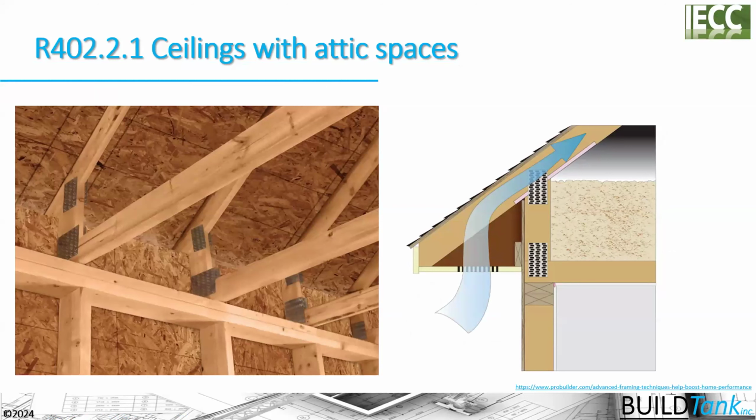And if we go back a few slides, you'll remember that R38 took somewhere between 10.5 inches and 14.5 inches in the two examples that I gave to achieve that depth over the top plate. So you're going to need a pretty substantial raised heel truss to do that.